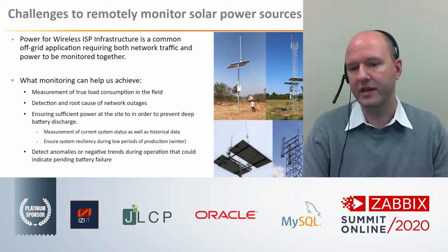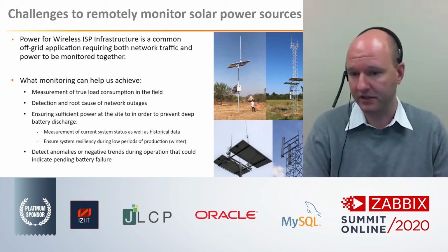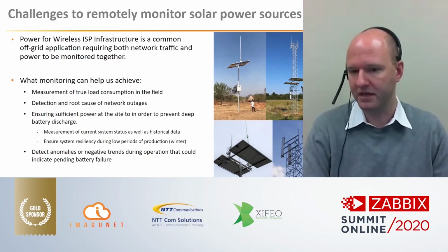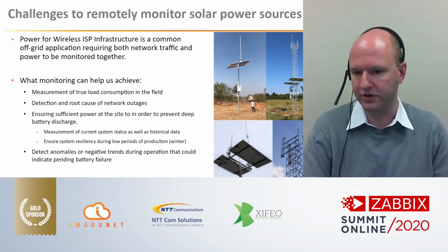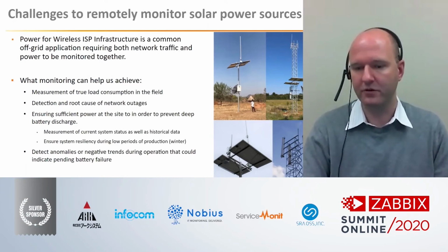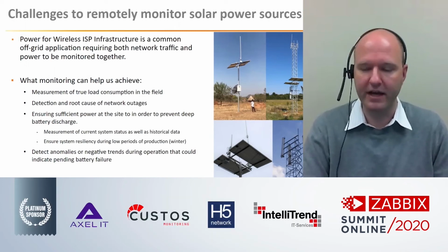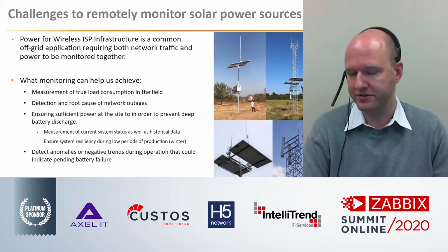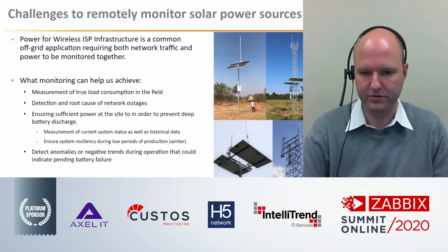But monitoring the end stage of a battery, which most likely will occur at some time in the system, since many remote sites that are deployed for an extended period of time possibly can go through 1 or 2 battery replacement cycles, is really critical to understand. And knowing when you have a downward trend where power is declining over time, and the battery is beginning to show signs that its health is no longer adequate to support the system, can be detected with this long-term data analysis.